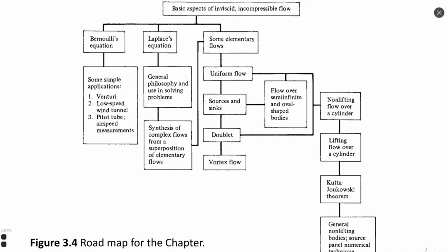And then the application of the Laplace equation in some elementary flows allows us to develop, when we combine these flows, some theories like flow over a cylinder, lifting flow over a cylinder, the general definition of the Kutta-Joukowski theorem, and numerical methods allowing us to calculate airfoils or other streamline aerodynamic structures that are used even nowadays, implemented in software like Xfoil.